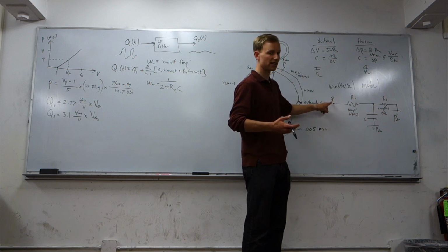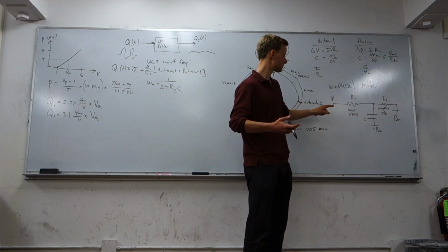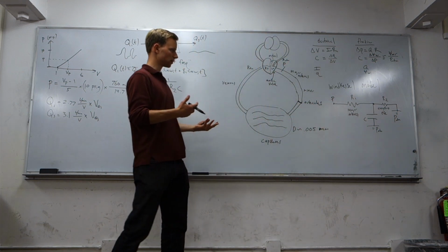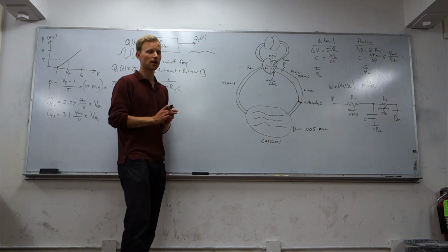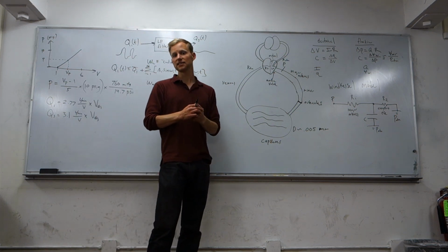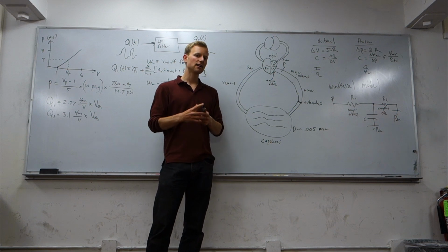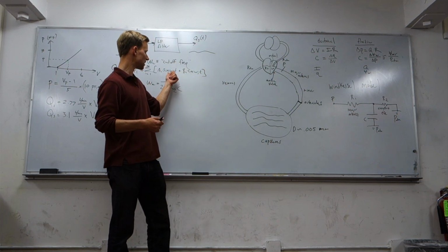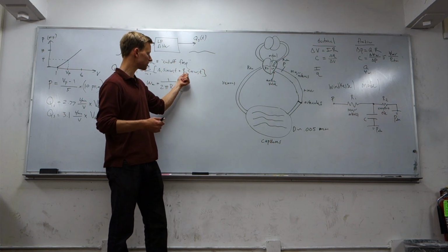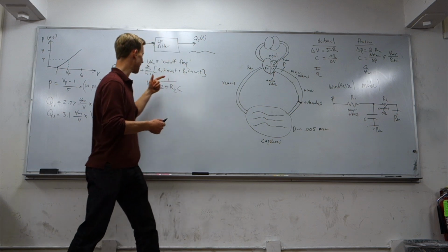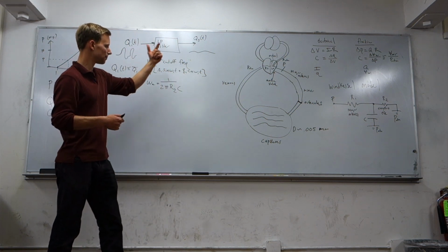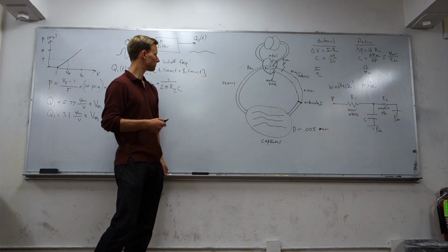We want to solve for P here. This is where our physical problem exists. So we're going to utilize the solution to the circuit, which is an ODE, and the ODE is already inside MATLAB for us, so we're not going to derive that here. And then we're going to pass in periodic signals, sines and cosines with different frequencies and amplitudes, into that ODE and get out what our pressure will be.